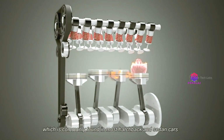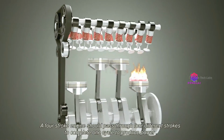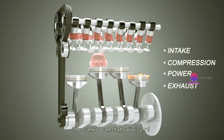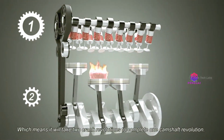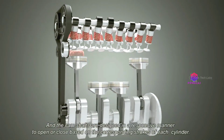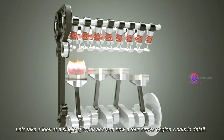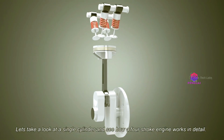and sedan cars. A 4-stroke engine should pass through 4 different strokes to complete one cycle to produce power. They are intake, compression, power, and exhaust stroke. The crank to camshaft ratio is 2:1, which means it will take 2 crank revolutions to complete 1 camshaft revolution. And the camshafts are designed in a responsive manner, to open or close based on the corresponding strokes of each cylinder. Let's take a look at a single cylinder, and see how a 4-stroke engine works in detail.